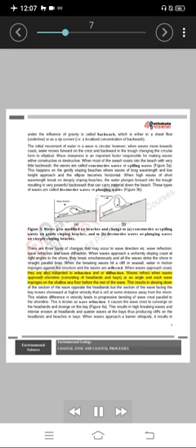Waves refract when waves approach shoreline consisting of headlands and bays, at an angle and each wave impinges on the shallow sea floor before the rest of the wave. This results in slowing down of the section of the wave opposite the headlands, but the section of the wave facing the bay moves shoreward at higher velocity that is still at some distance away from the shore. This relative difference in velocity leads to progressive bending of wave crest parallel to the shoreline. This is known as wave refraction.